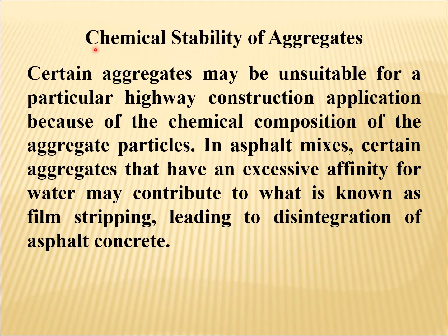Okay, now chemical stability of aggregates. Certain aggregates may be unsuitable for a particular highway construction application because of the chemical composition of the aggregate particles. In asphalt mixes, certain aggregates that have an excessive affinity for water may contribute to what is known as film stripping, leading to disintegration of asphalt concrete.